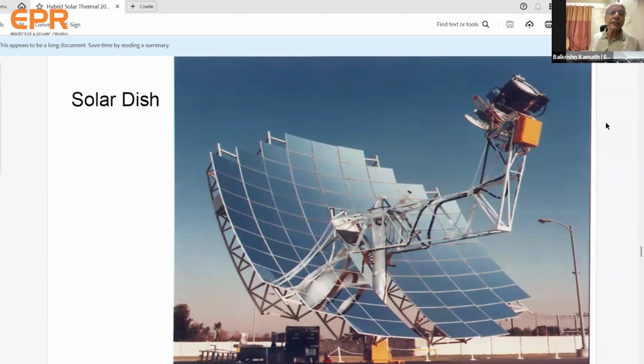This is solar dish technology. This is also 2 axis tracking, but here the receiver is very near, at the focal point. This is a parabolic trough in 2 sides, a paraboloid you can say. In both sides the curvature is there, so it is a point concentration. Here also the temperature goes up to 1000 degrees. Here the receiver is a tube structure, running either oil or molten salt, and then the liquid is taken out and brought to a heat exchanger.